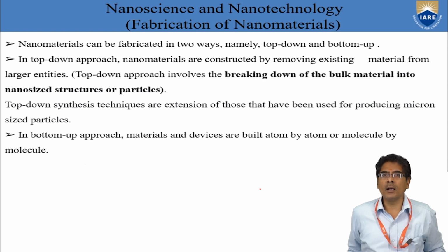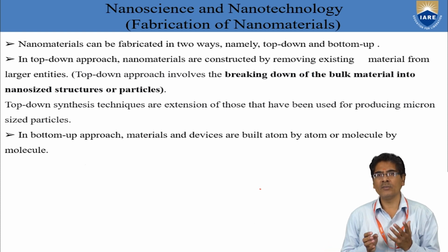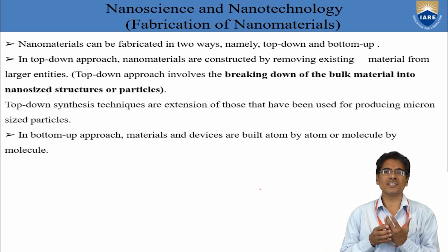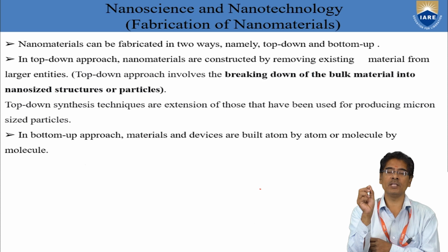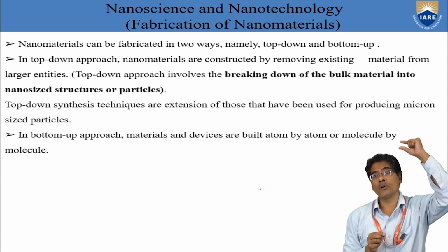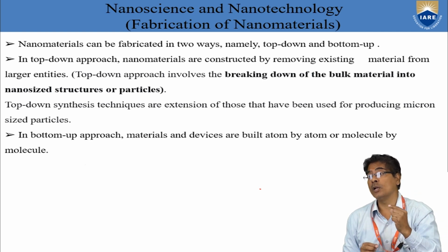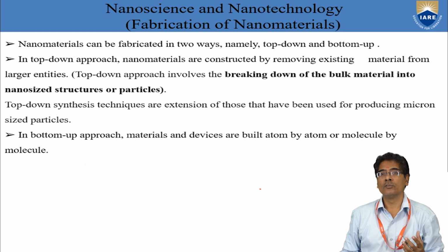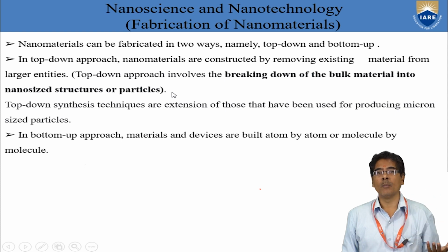In top-down synthesis, the techniques are extensions of those that have been used for producing micron-sized particles. So the particle size should be in the range of micron-sized particles. In bottom-up approach, materials and devices are built atom by atom, or molecule by molecule, or by cluster by cluster. So this is what we speak about, some of the fundamentals regarding the fabrication of nanomaterials in top-down and bottom-up approach.